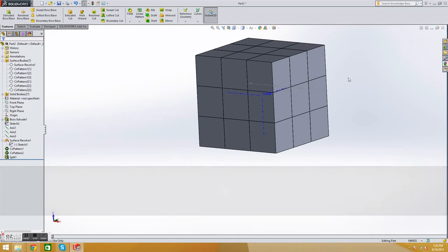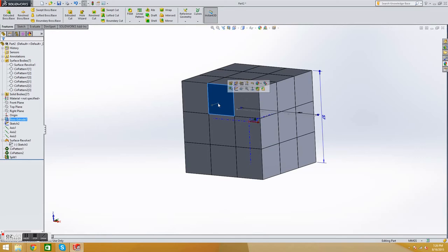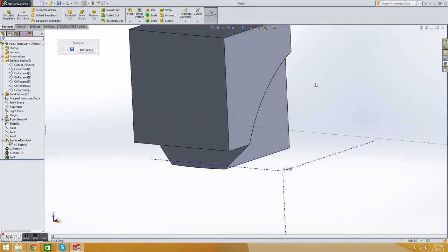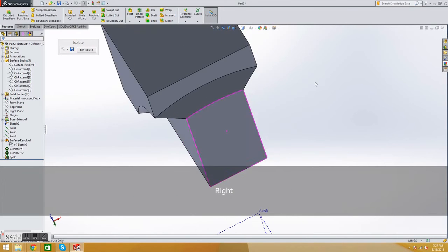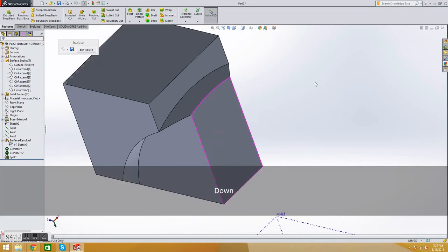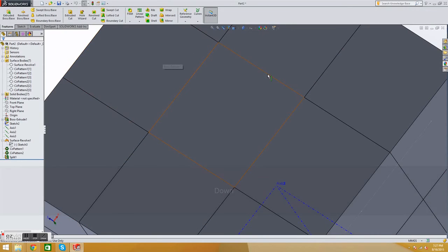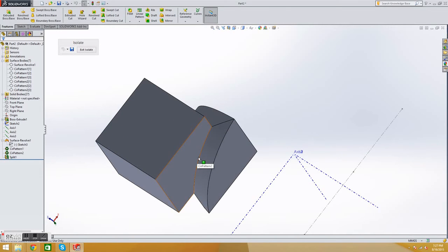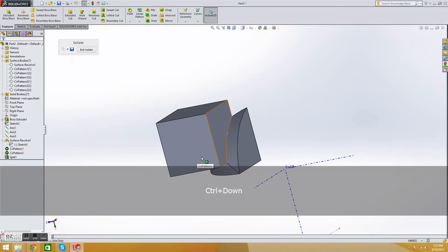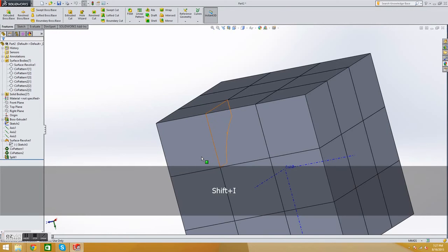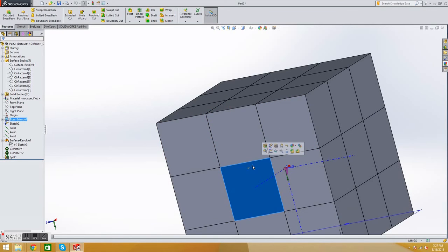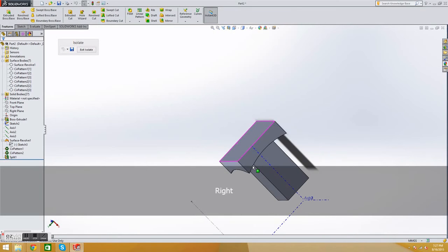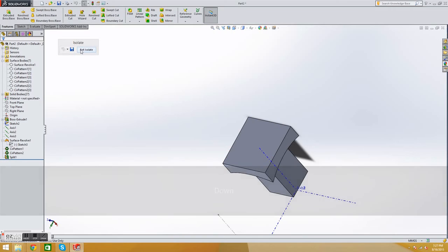So what you can do is, I don't know, click on an edge, press I. What that does is that isolates it. And now you see the edge. You can look around at it. That's an edge. Looks like the edge of a 3x3. Isolate, or you can press Shift I for that. So press I here. This is the corner. Click a corner. Look around on it. Looks pretty good. Press Shift I to exit isolate. You look at a center. Press I, isolate. Looks like a pretty center. Cool. So if you've done this, you have designed the basic parts of a 3x3.